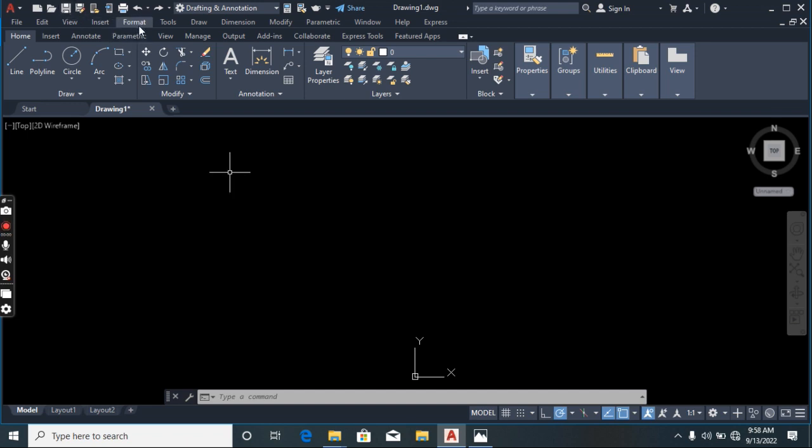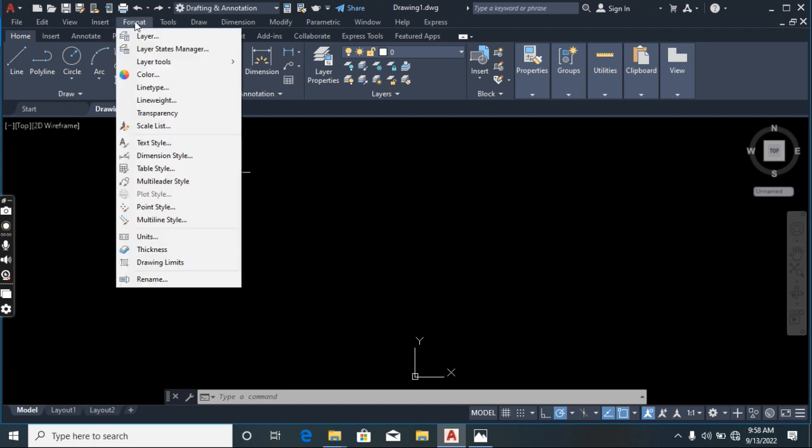In the menu drop-down bar, you see that there is Format. You go under Format, and those settings that we left untouched, you see them. Drawing limit. So we say let's just leave drawing limit. That will be achieved at the end of our drawing. Maybe you want to print out our drawing, you want to print it on A4 paper. This is where we can set our drawing limit on our printer, so there is no need of a drawing limit here.